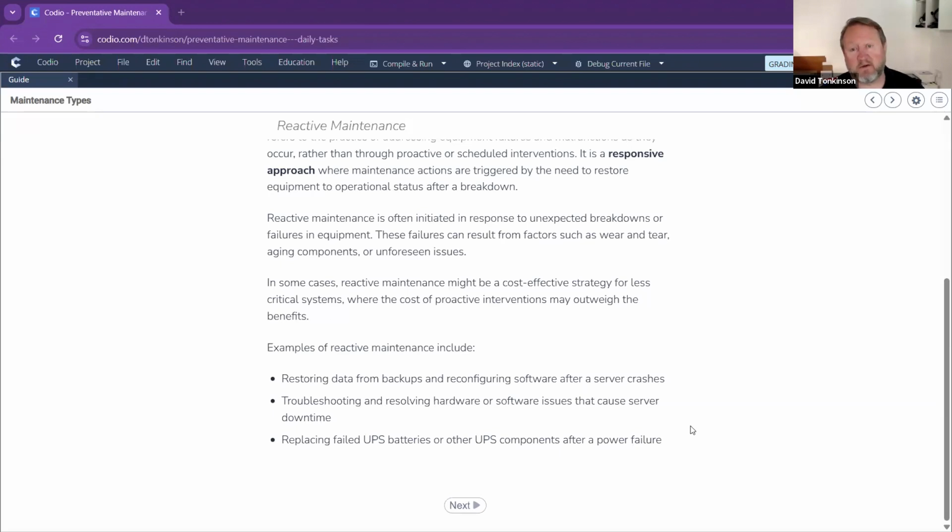Main operation continuity. When we talked about dealing with the HVAC systems, or building HVACs, you talk about having enough HVAC systems and capacity to keep that room cool, and then some more. So you're looking at the 2N+1 situation where we've got more capability of keeping things cool, more separate systems.